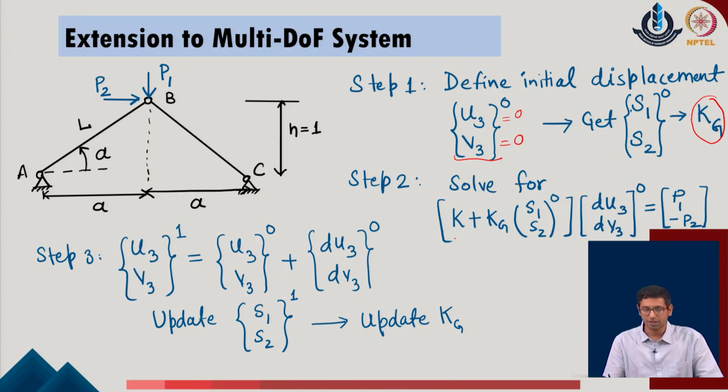Now, solve the given system for this initial value and obtain the increments in the displacement with respect to any kind of increment provided in the loads of the given system. So, you provide the load increment, either with the values applied in full, where we can apply it in one single step, or we can also go with this P1 value. If say this is the load of 10 units, I can go with an increment of 2, then the next increment of 4, and the next increment of, say, again 4 in the given system. So, the user can apply the loads in particular increments on the given system, which are defined by the user itself.